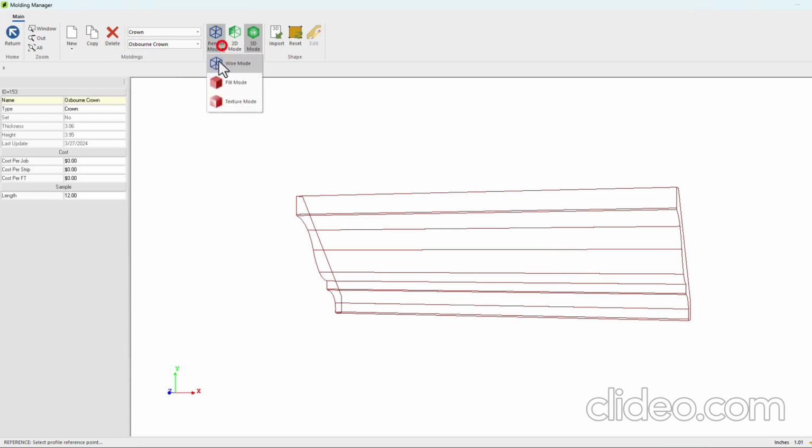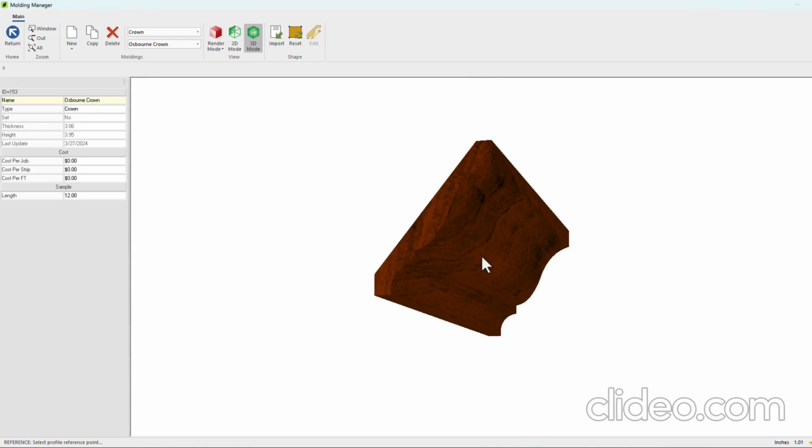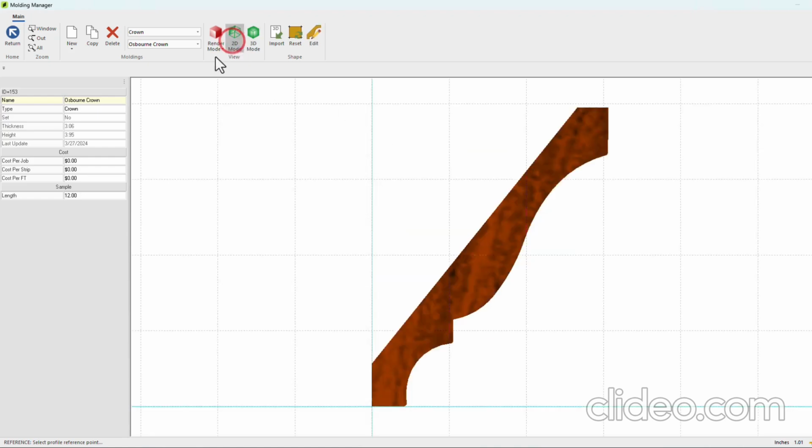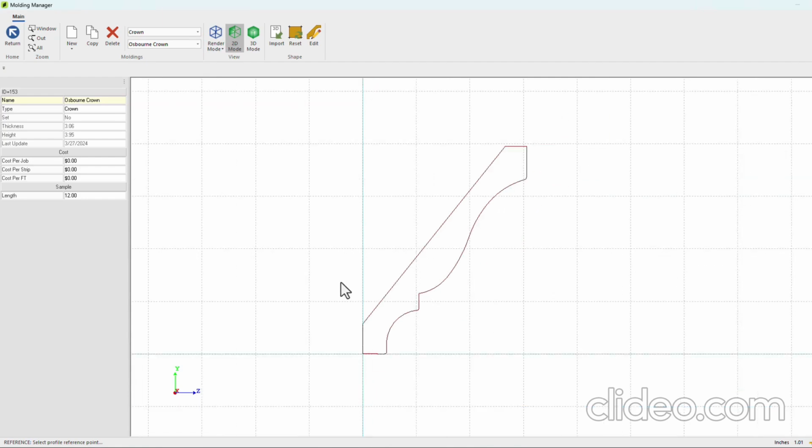we can see we have a nice looking profile. So that was pretty easy, right? Now, obviously there's hundreds of moldings, but at least we have a workable DXF. It's not always that nice, because sometimes you'll find that either there are too many layers where you can't get it cleaned up, or the actual points in the profile are just incorrect, or there are too many, or something just might not be working right.